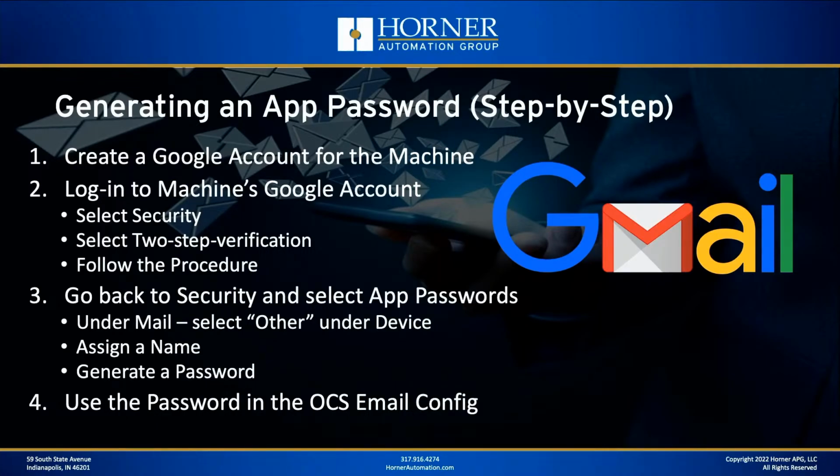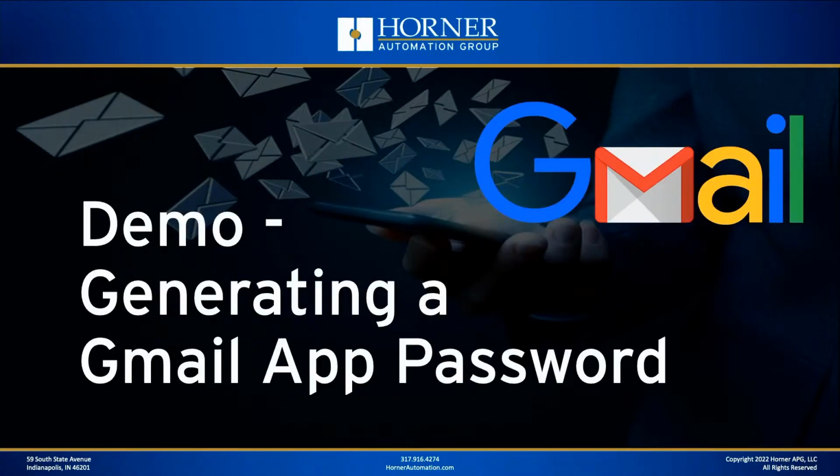Now, there are two ways you can do that, of course. You can hard code the password, which is an option, or maybe better yet, if you've assigned a variable to the password, you can go into the OCS from the touchscreen somewhere, maybe in a protected screen, and type in that new password from there. Then if it ever changes again in the future, you don't have to fire up Cscape to rectify that. So that's the procedure I've described here on the slide. Let's go ahead and do that on the computer next.